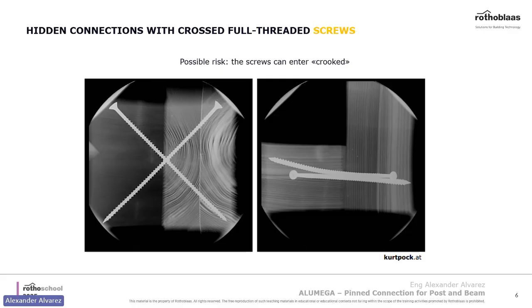You can see here one of the screws was trying to come off the side; if it was a bit longer, instead of going into the middle of the beam, it could have come off. So it's not always the case. An experienced installer would know how much force to apply, or to drill it perfectly. But it's just something to keep in mind.